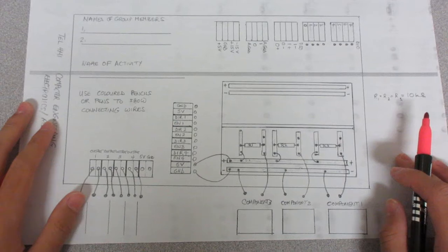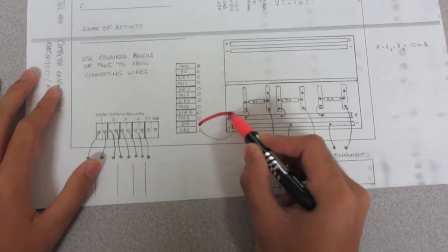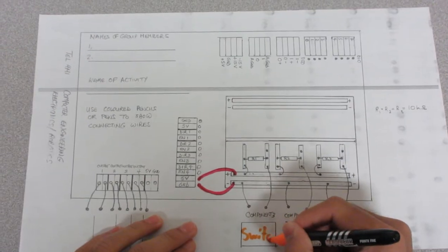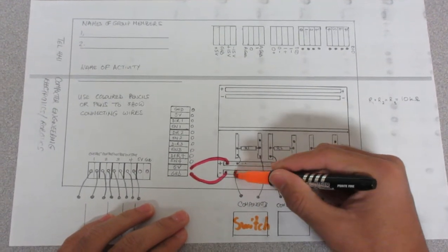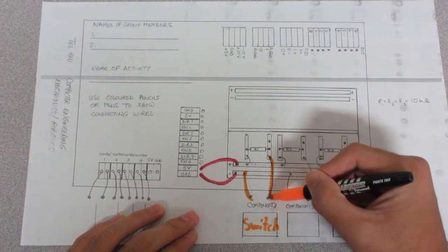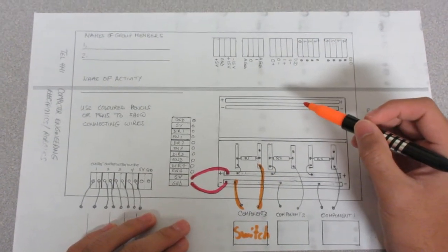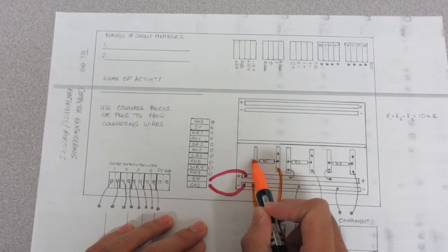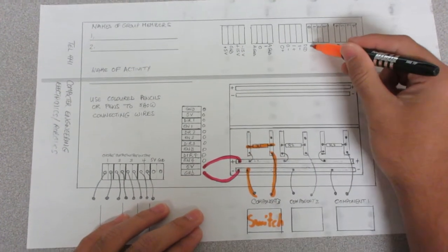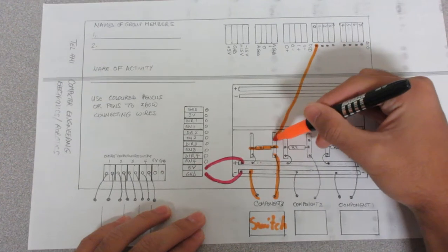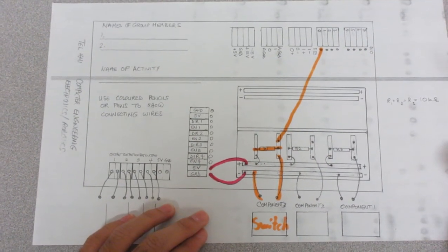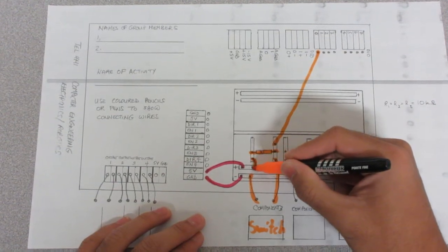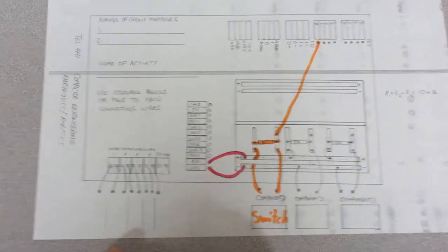Use 2 of the wires to connect the 5V to the positive on the breadboard and the G and D to the negative. To wire the switch, connect 2 on the switch to the negative on the breadboard and 1 on the switch to a row on the breadboard. In the same row, add a resistor and another wire, which is to be connected to DIO0. Using another wire, connect the wire in the same row as the back end of the resistor to the positive on the breadboard. That's how you wire the switch.